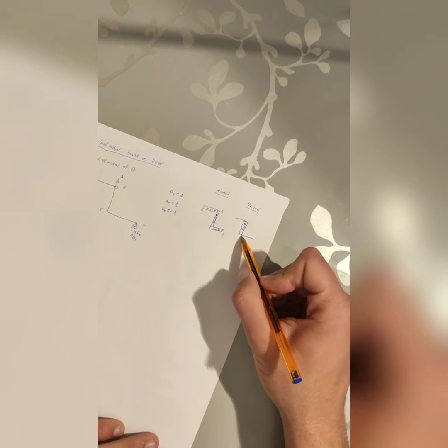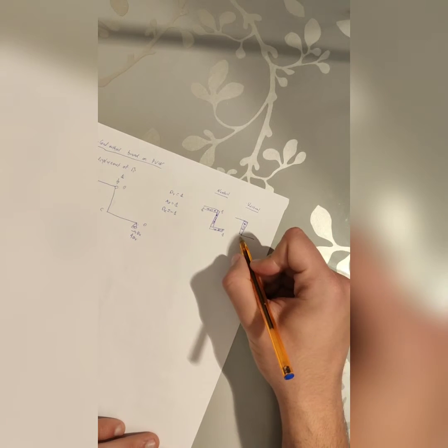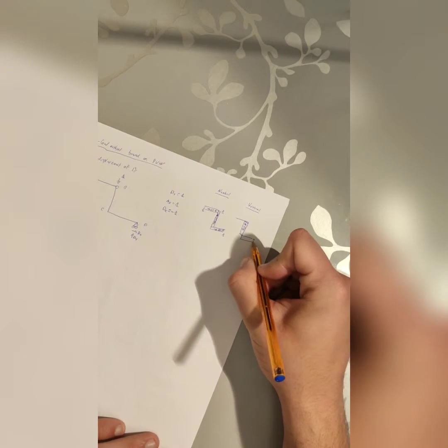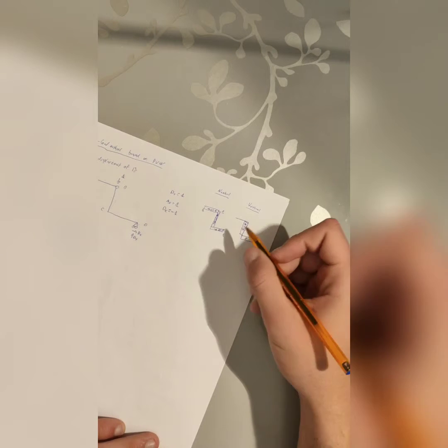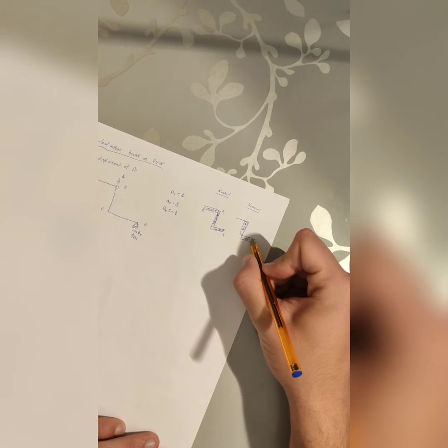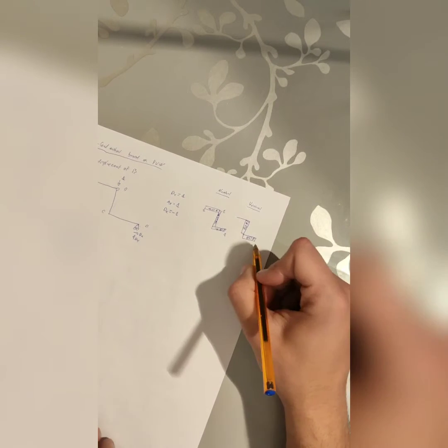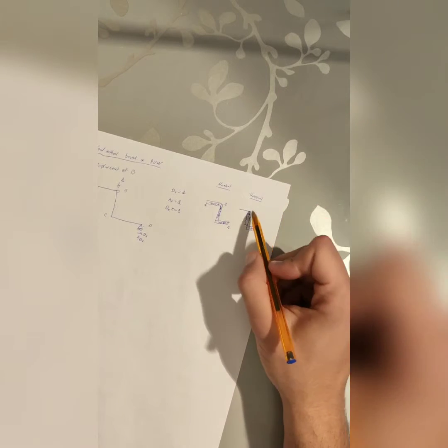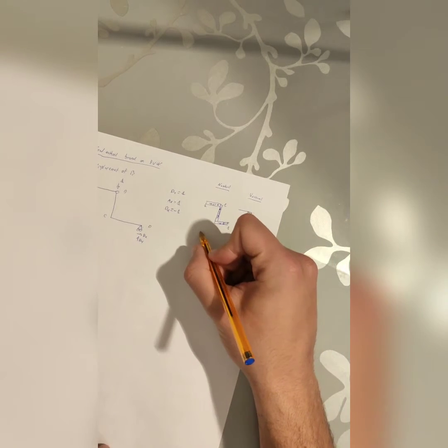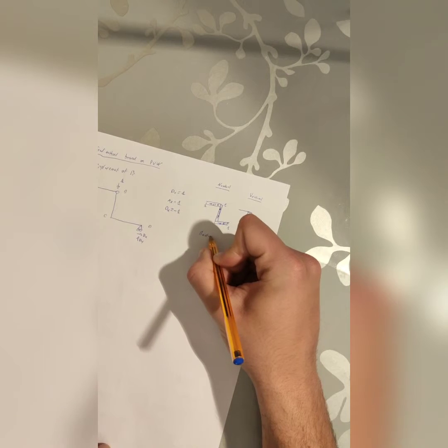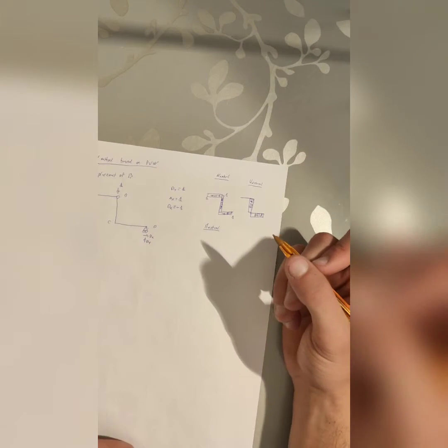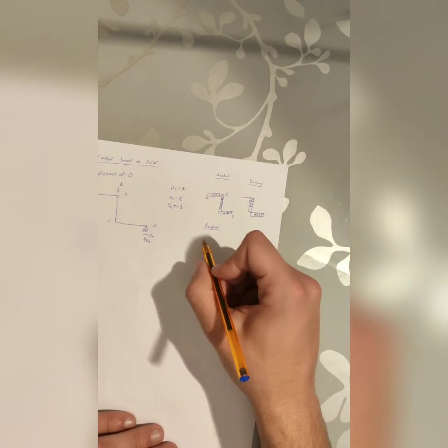And in the bottom part from C to D, we can call it negative, but the forces on the left are downwards, and the force on the right heads up. And with this shear diagram, we can calculate the moment diagram, which is the more important one, and it will help us to calculate the displacement.